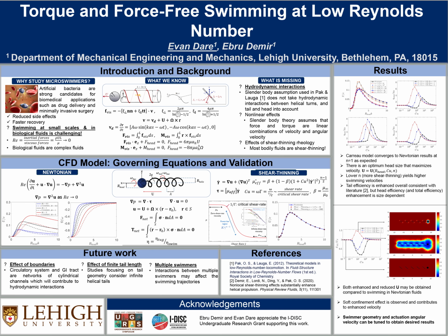Non-dimensionalizing the Carreau constitutive equation, we found a relevant non-dimensional number called the Carreau number, which is the ratio of the applied shear rate to the critical shear rate, the rate at which the shear-dependent viscosity reduction becomes prominent. When the shear-thinning index, which is the exponent in the power law region, is 1, solutions from the Carreau model are expected to converge to the Newtonian solution, which is how we validated our shear-thinning simulations. The results from the Newtonian model and the Carreau model with a shear-thinning index of 1 are identical.